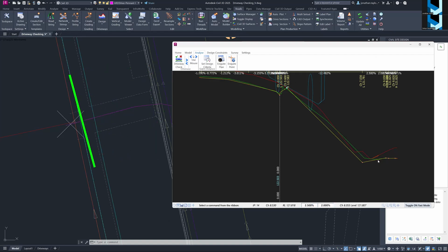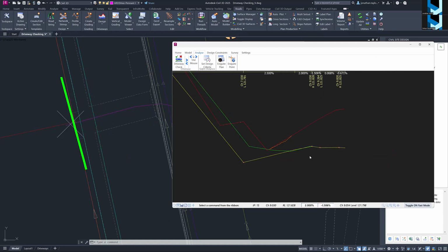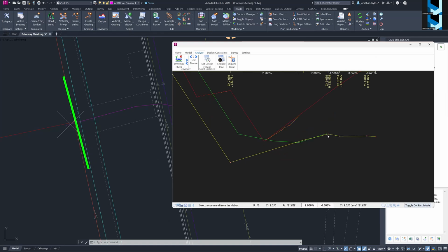We can also change, which you can see down here, the footpath, which I've put in, which is connected to the natural surface, 0.5 meter at the, what was it, 2%? Can't remember. It's written right in front of me. 2% for 0.5 meter, and then 2.5% for that 1.5 meters. So I've got scope to go in and change that part if that wasn't so much of a constraint. But this was just to give me an idea as to whether or not, by putting in the footpath in this manner,